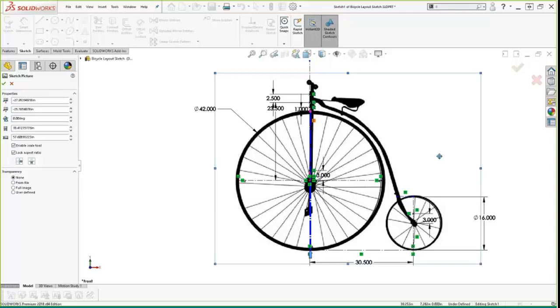The in-context editing is done specifically so that you can get things into the right place. Once you have all the components created, all the individual solids created, you actually have to break most of those in-context relationships to create the tolerancing. There are a few you might keep to help change sizing and so forth, but you're still going to want those reference dimensions along with their tolerances added when you go into a drawing mode.